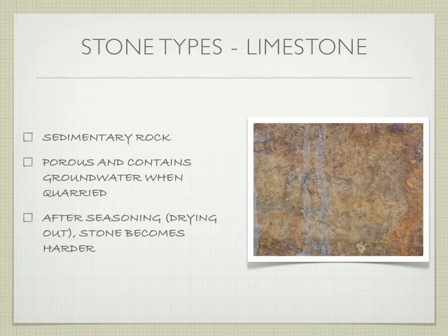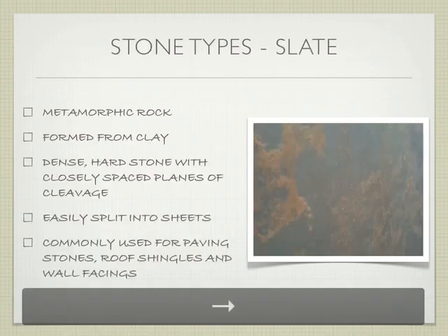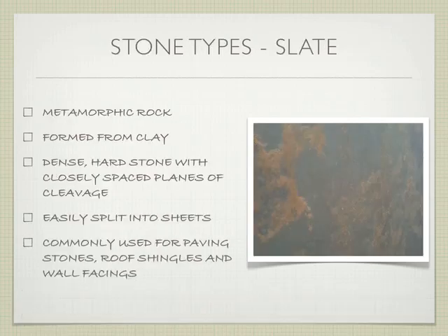If you're in Italy, a lot of the buildings actually have limestone cladding. And Italy does get rain, more so than Los Angeles. So it can work. It just depends on the grade of the limestone, how many holes are in it, how filled it is, and that sort of thing, recognizing that it can absorb some of the water.